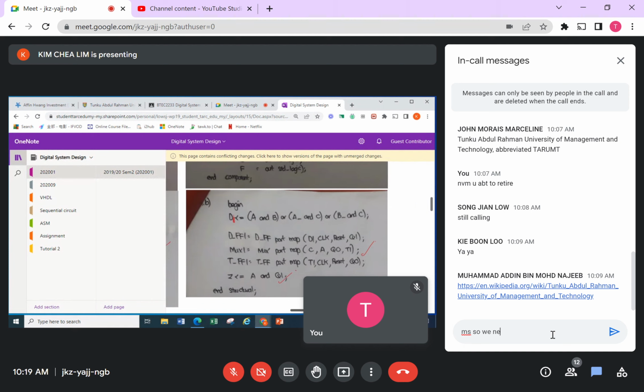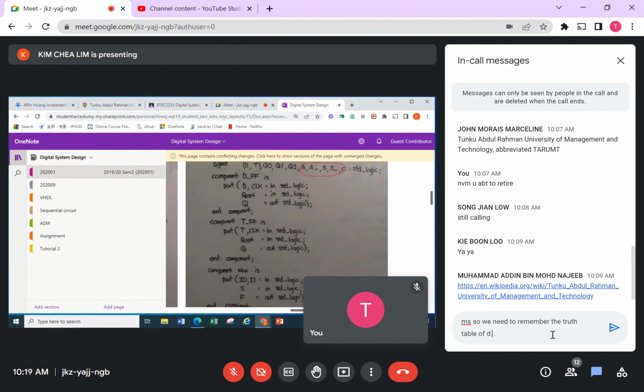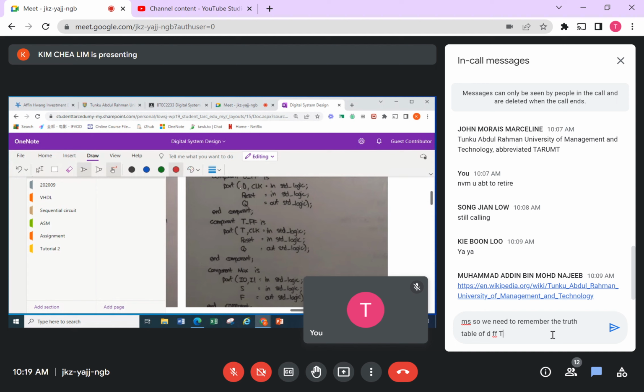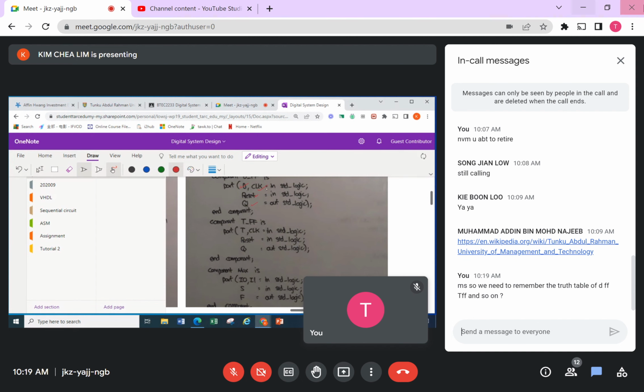So check here: first is input, second is clock, third is reset, fourth is the wire Q1. Double check that this is correct. D1 is connected to your D, go by position. Clock connected to clock, reset still reset, and Q is the one that you connect to Q1. That's why you always arrange in order so that you don't make mistakes.